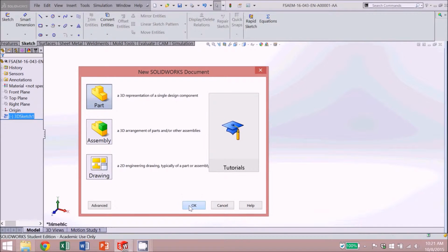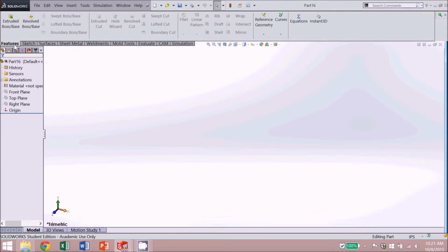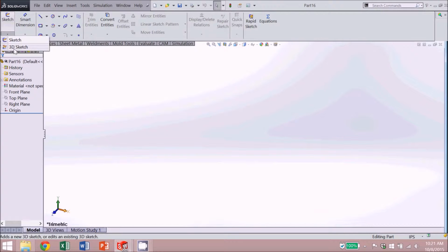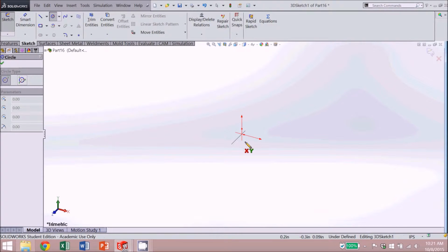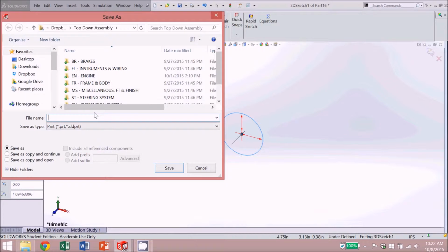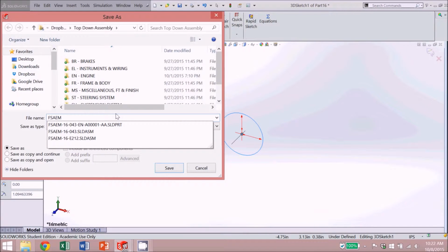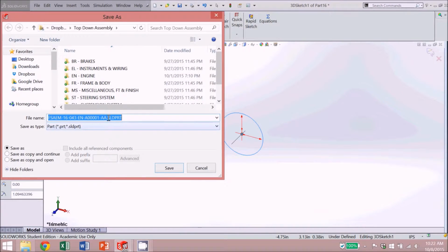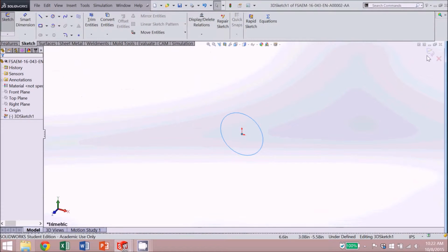And let's go ahead and make one more part because we're going to be using it in the future. And hopefully we can show you the importance of the guide sketches. If you ever need to change the plane you're drawing in with a 3D sketch, press Tab. Make sure to close these so we can edit them.